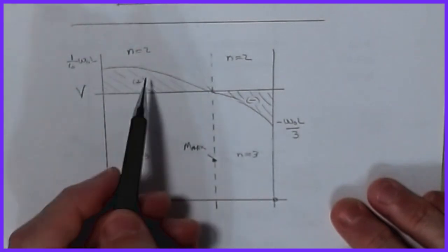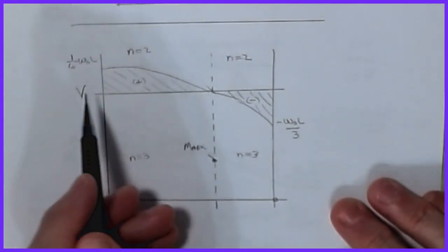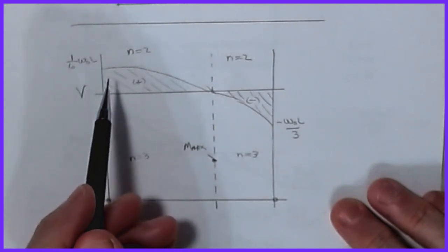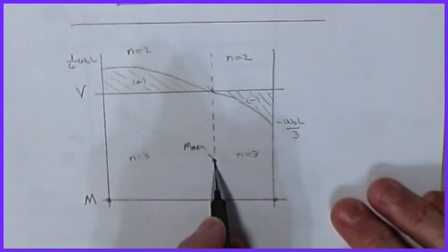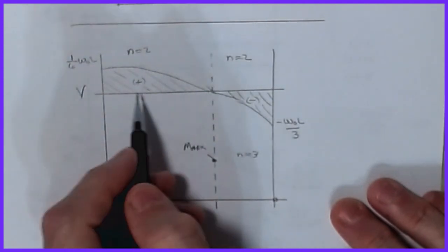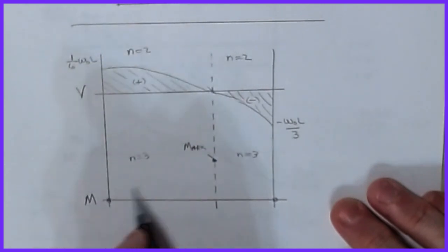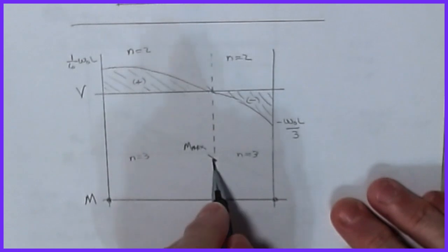That worked very well when this was linear or constant. But with n equals 2, this becomes a bit of an issue. So most often in design, I don't worry about what the values in the middle are doing. I just need that maximum value, because if I design for it, I know I'm going from 0, I'm increasing because that's positive, and all these other values fall between M max and 0. So if I design for it, I'm good.